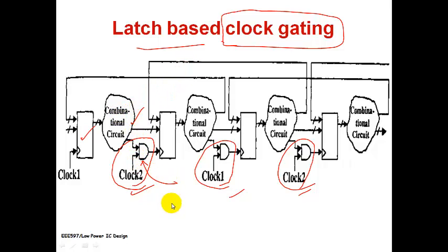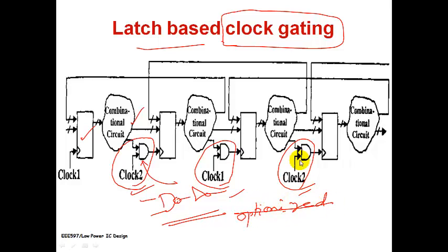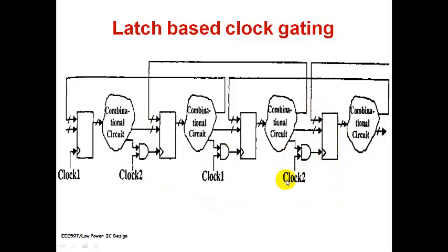If it is an AND gate, naturally it would be an AND gate followed by one inverter, and this particular gate should not be taken by the tool, for example Synopsys, as a gate component which is to be optimized also. So we have got to put, it shouldn't be optimized. This you introduce it just for the purpose of clock gating and timing the sequence of data flow.